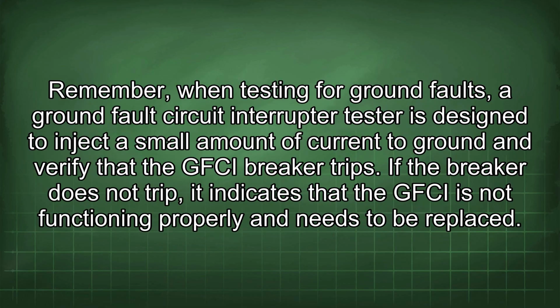Remember, when testing for ground faults, a ground fault circuit interrupter tester is designed to inject a small amount of current to ground and verify that the GFCI breaker trips. If the breaker does not trip, it indicates that the GFCI is not functioning properly and needs to be replaced.